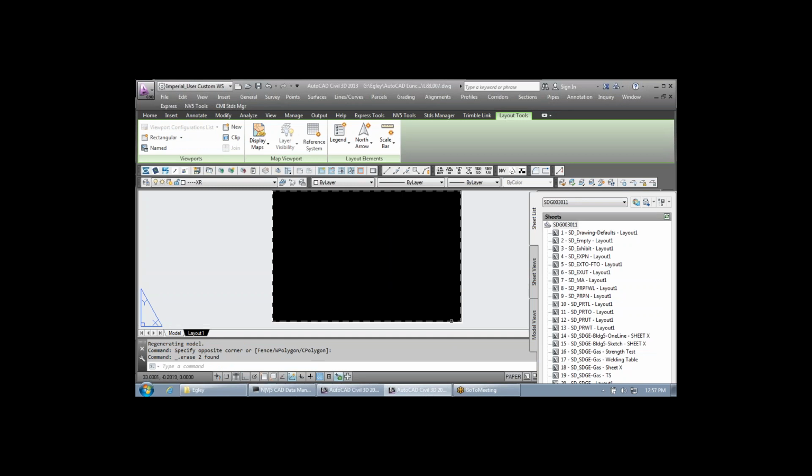So typically, what do we do with our title blocks? We'll have our current sheet number in here. Wouldn't it be nice if we never had to edit that piece of text or that block? Well, let's make it so that we don't ever have to do that. Especially when you have a 150 plan sheet set or 180, and then you add a sheet in your middle, and then you'd have to open every sheet and change every single current sheet. Right? So let's think of a clever way to get around that.